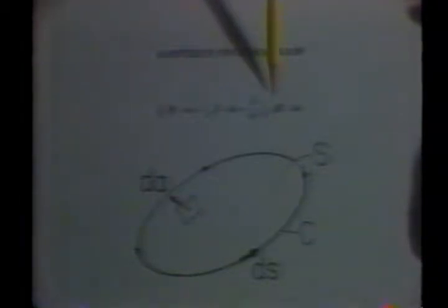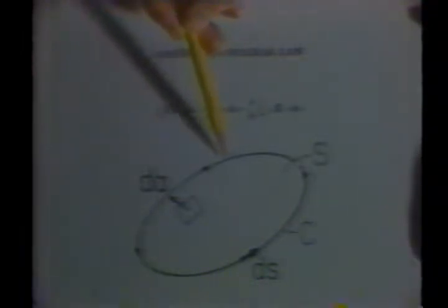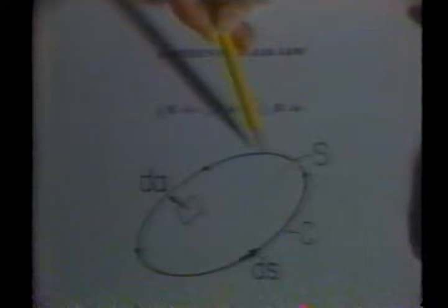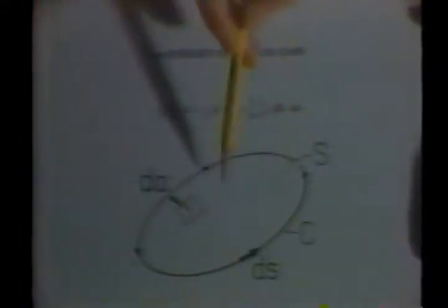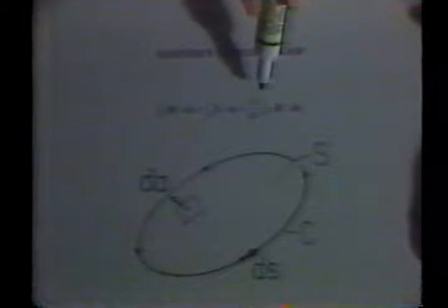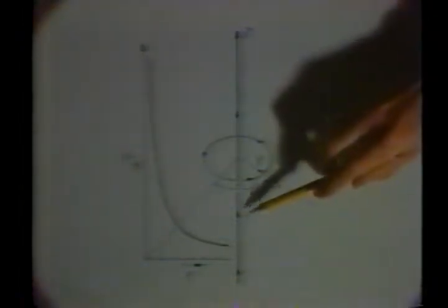In this demonstration, the current density and associated fields are at 60 Hertz. Current essentially extends to minus and plus infinity. This line current passes through a surface S enclosed by this contour C. Ampere's law says that there is an integral of H around the contour C. Symmetry requires that only the azimuthal component of H be non-zero and that this component only depend on the radial position R.